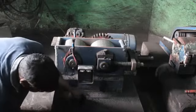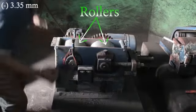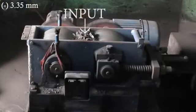This jaw-type crusher can reduce the sample size to less than 12.5 millimeters. This is a roller-type crusher which can further reduce the sample size to less than 3.35 millimeters.